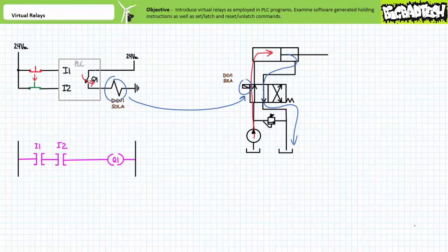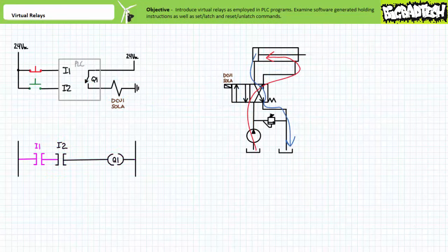Note as presently implemented, this PLC program does not maintain the last asserted state, and due to the momentary nature of the field input device on input 2, the valve remains in the straight-through position and the cylinder remains extended only when the green push button is actively being held closed. As soon as an operator releases the green push button, the make instruction examining I2 does not permit logical continuity and output Q1 is immediately deenergized. The spring offset valve would return to the cross-connect position and the cylinder would retract.